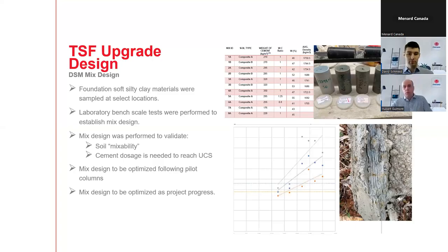So the first very important thing is to collect samples and run some mix design bench scale tests in the laboratory to validate the soil mixability and also the cement dosage that's needed to meet your design criteria.